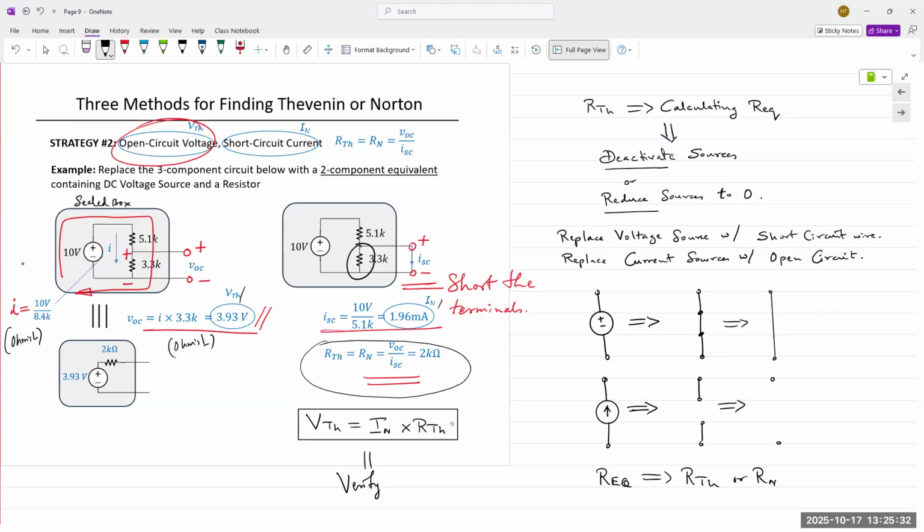If it is 0 ohm resistance, it doesn't matter what is connected in parallel. Nothing will go down the other pathways. Everything is going to flow through that 0 ohm pathway. So if there's current coming from our source, comes down here, comes through here, well, it should go through here and here, but because the resistance is 0 on the right, everything is going down here.